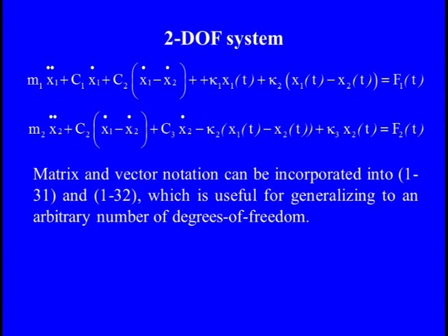So we have the undamped natural frequency and the damped natural frequency. We can simply calculate whether the system is underdamped, critically damped or overdamped, and accordingly we can frame the equations for the solution. And then we can find out what the outcome is, x2 by x1 according to the mode shapes.